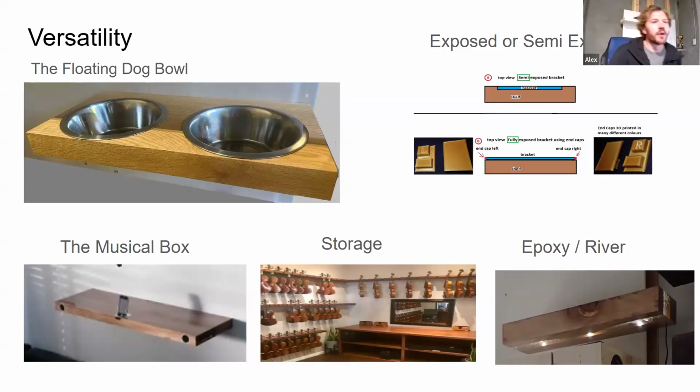That way, it would basically be an exposed bracket. But again, there are other options without needing to router, right? Like if you get a three corner folded MDF, you just fold it around and then you've got that space. Or like the shelf we put up, for example, that one didn't require routering because they just put the laminate around it and then built the box on the inside with a strip. So again, no routering required. But of course, if it's a full wood shelf, then you kind of have to router unless you're doing that exposed bracket like that. So yeah.